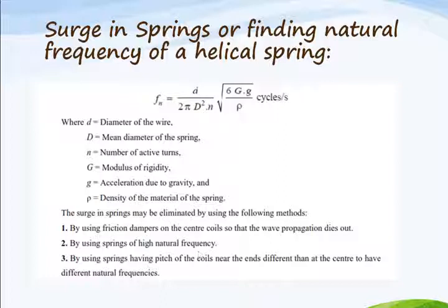If the equipment frequencies are at some value, you need to take a higher natural frequency helical spring to compensate those frequencies of that equipment. If you take higher natural frequency springs, then that can be eliminated.